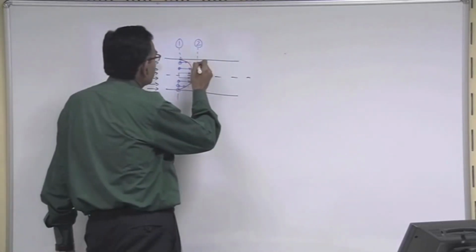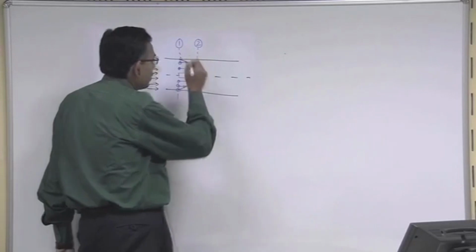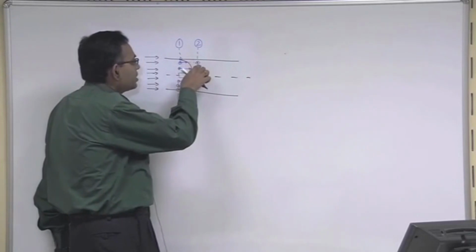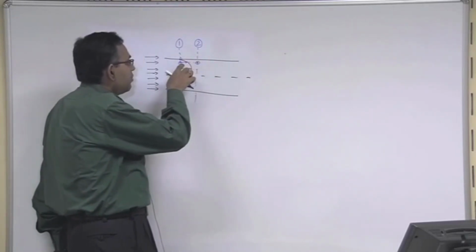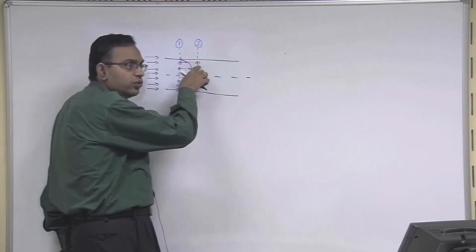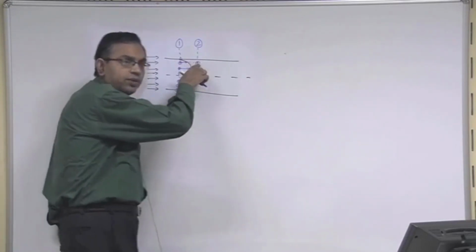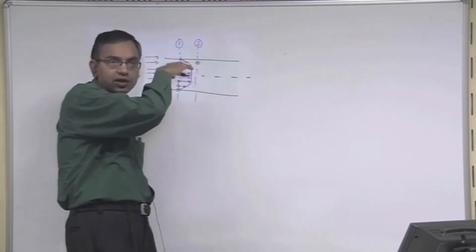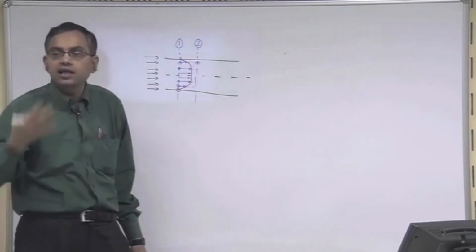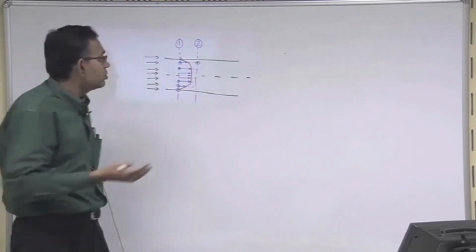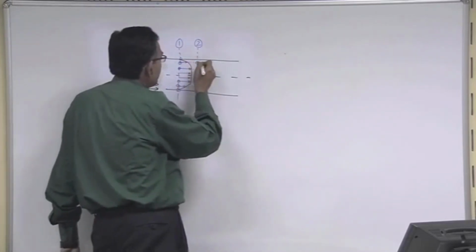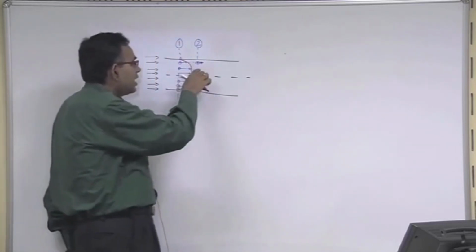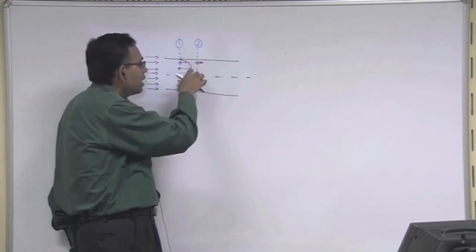Now you come to this section. Can you tell whether the axial velocity at this location, compared to section 1, will be more or less at section 2? It has to be less, because now the fluid has come in more intense contact with the solid boundary, so it is more seriously decelerated. That means it will take a greater distance from the wall to come to the maximum.